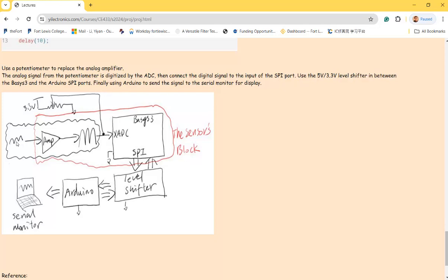It could be an analog signal sitting on like 1 volt, swinging around 1 volt, 2 volts, 1.5 volts. It's all possible. And the voltage range of the signal could be 100 millivolts, 150 millivolts. So you need to filter out the offset first to bring it down to 0, so it's swinging around 0.